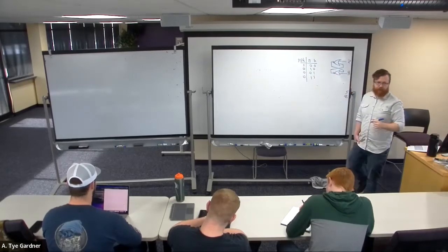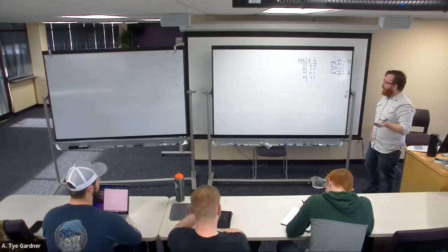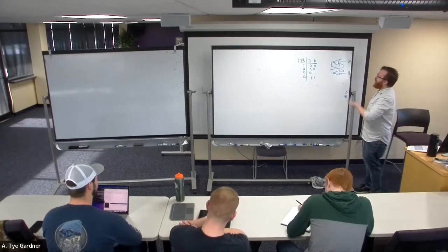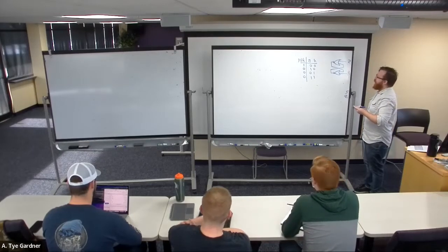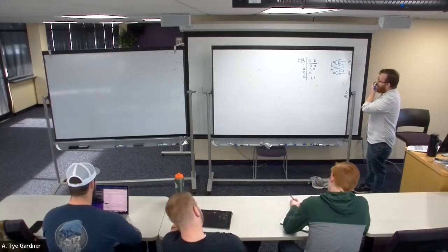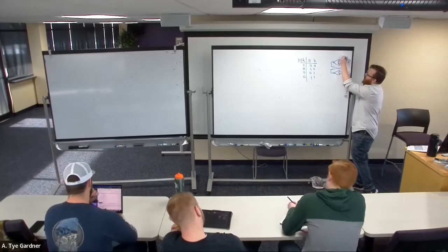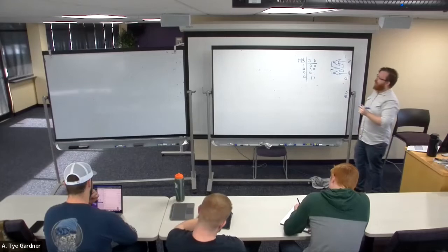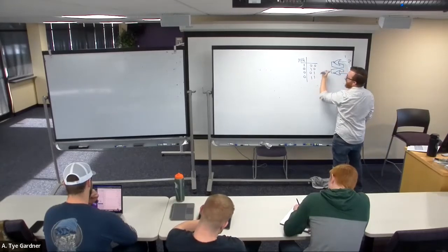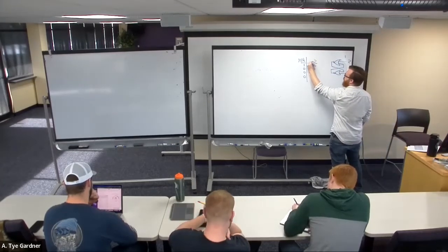That's NOR. So now I can go ahead and make an assumption about what S is doing and what R is doing. And because it turns out to be much easier, I'm going to set S to 1 and R to 0 to start. So I'm going to rename these from A to B, and I'm going to say this is S, this is R.